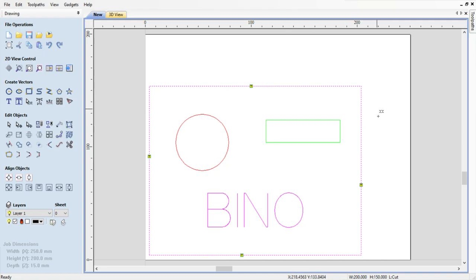Ang advice ko lang when making tabs, iwasan yung magkaroon ng tab sa corner. Bakit? Halimbawa yung mga ganyang corner. Kasi yan yung tabs na mahirap tanggalin, mahirap linisin. Kasi what would happen is, ito, butas ito continuously, tapos may tab dito, di ba? So, pwede tayo magsingit ng saw o lagari dito para maputol ito. Pero itong corner, medyo mahirap siyang putulin ng lagari kasi you have to be coming from both sides pa. So, alisin natin lahat ng corner.